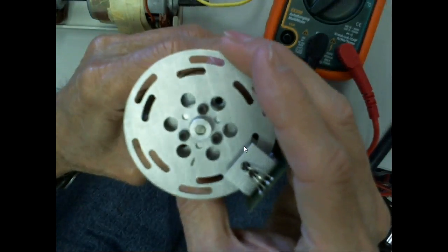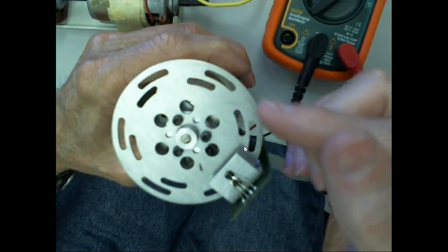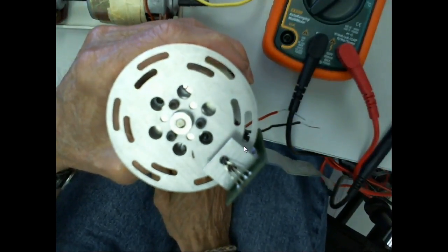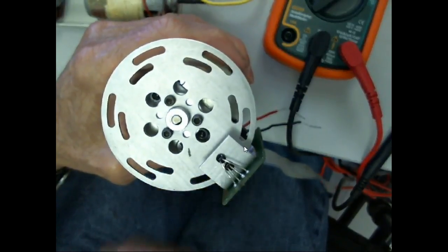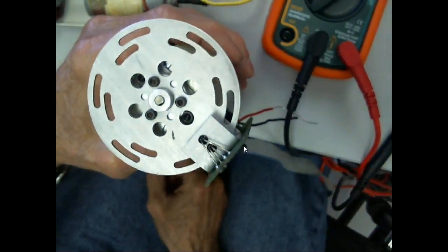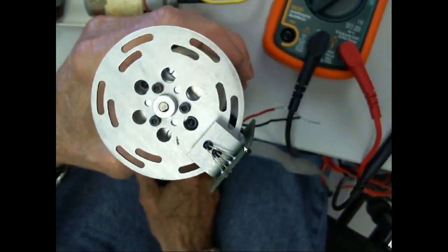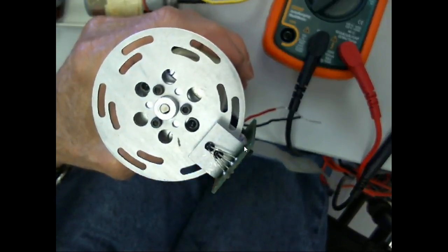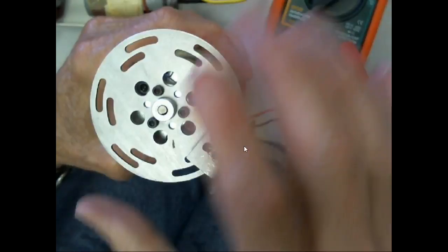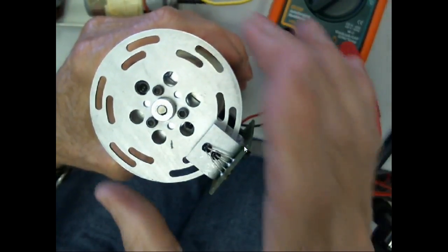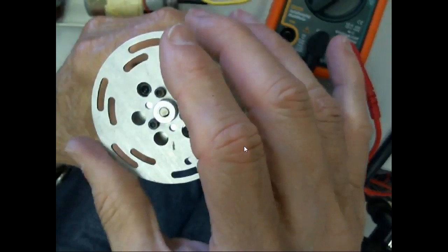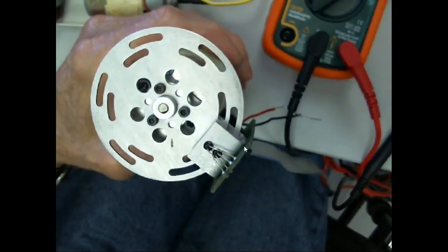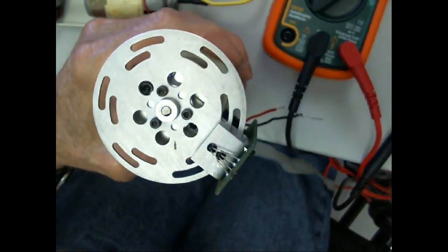So what we're doing here is we're using an encoder. Now you can use either one of these to sense speed. You wouldn't use both of them to sense speed, right? You understand? So this is a quadrature encoder. And what's the advantage of a quadrature encoder? What does it give us in speed? Not only that, we can get 3 things out of a quadrature encoder. I think you said one. We can get what? Speed, direction, and position. On an incremental encoder, the only thing we can get is position and speed. Everybody make sense?